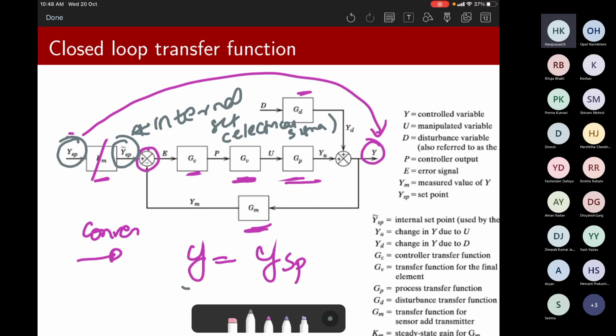To do a simple job, we put in a lot of things, because all of them cannot work alone. To aid the controller, you put in the measurement device. To operate the process, you put in the valve, and between them, the I2P is virtually missing in this. So I2P could also be added between the controller and the valve, if that is the case. Otherwise, this I2P conversion is 1.